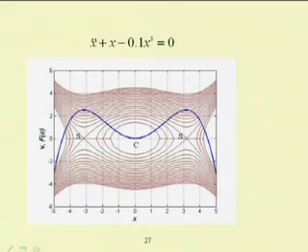Those equilibrium positions you can find by substituting x dot equal to 0 and finding the value of x. So, you can find the value of x and corresponding x dot, and you can plot the flow or the potential well. This is known as the potential well. Corresponding to the minimum potential you will have a periodic response, and corresponding to the maximum you will have an unstable response, which corresponds to the saddle point.